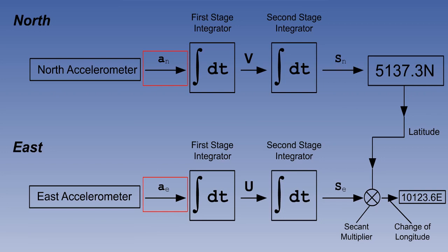This would be disastrous. As we said, the integrators would not know that these false accelerations were really components of gravity and would start integrating them, thereby generating false velocities. A constant acceleration would very rapidly build up into a very large velocity. Think what happens when you hold the accelerator pedal down on your car. These rapidly increasing velocities would then be passed to the second stage integrators, where they would very rapidly build up into distances gone. We would have a runaway system, all this whilst the aircraft is still on chocks. This must not be allowed to happen.